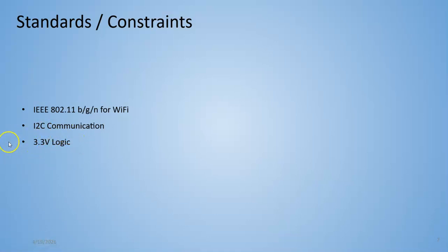Standards and constraints: I've had to use 4 standards. This particular set of devices uses the IEEE 802.11 BGN standard for Wi-Fi communication, and for the circuits themselves, I'm exclusively using I2C communication, and this part here is important, the 3.3 volt logic.